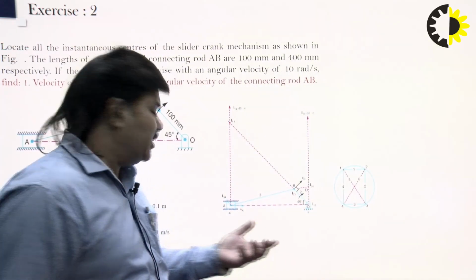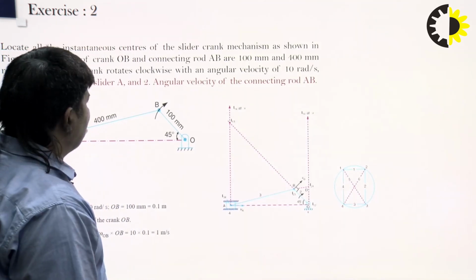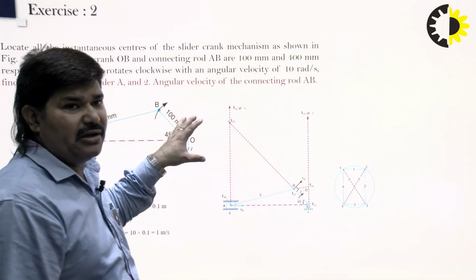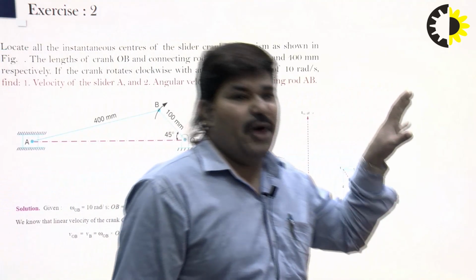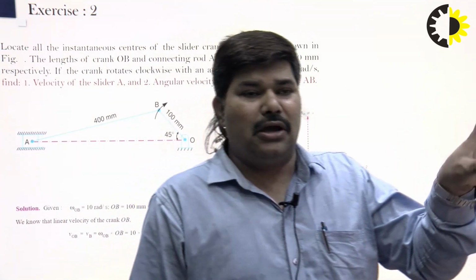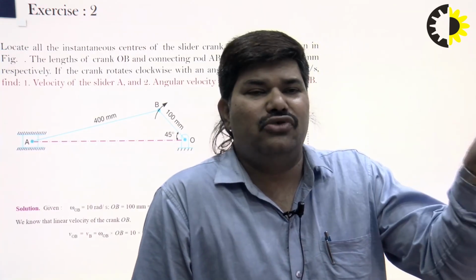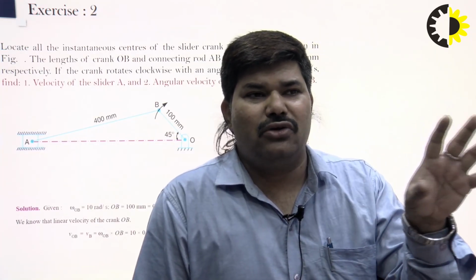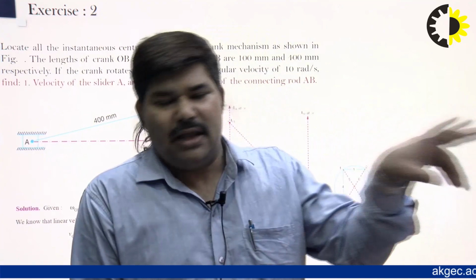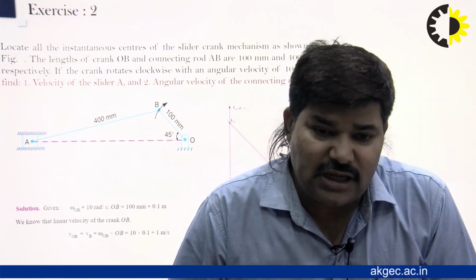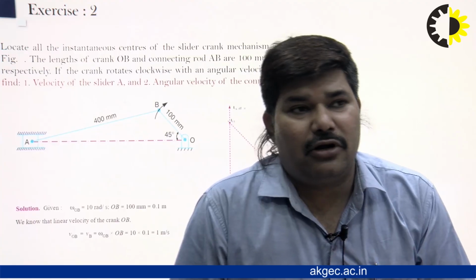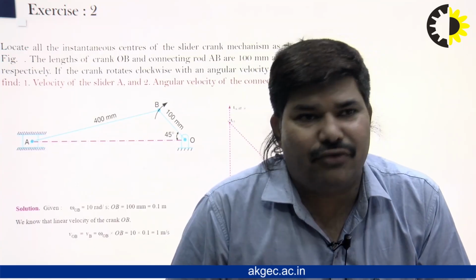Again, the 4 links are there, with crank length A, B, C, D all given in the figure. So we draw the same patterns with the same parameters. We take the point O, use the protractor, take the lengths according to that, mark them, and then you can draw. So these are the basic geometry for drawing the slider crank mechanism or the 4-bar mechanism.